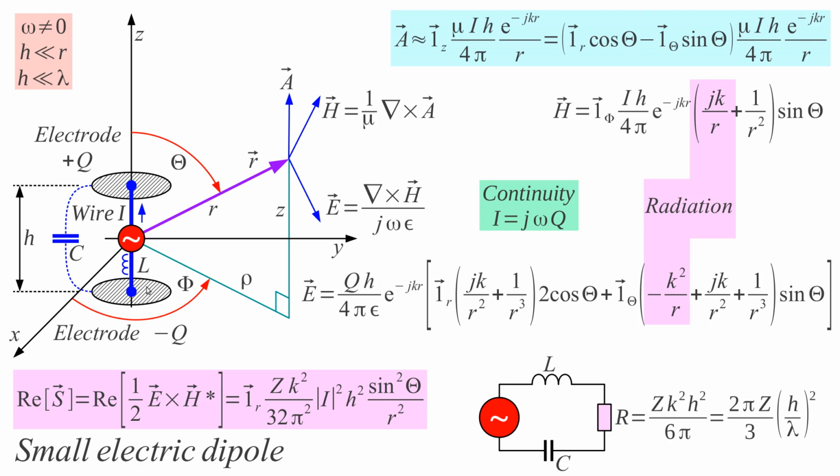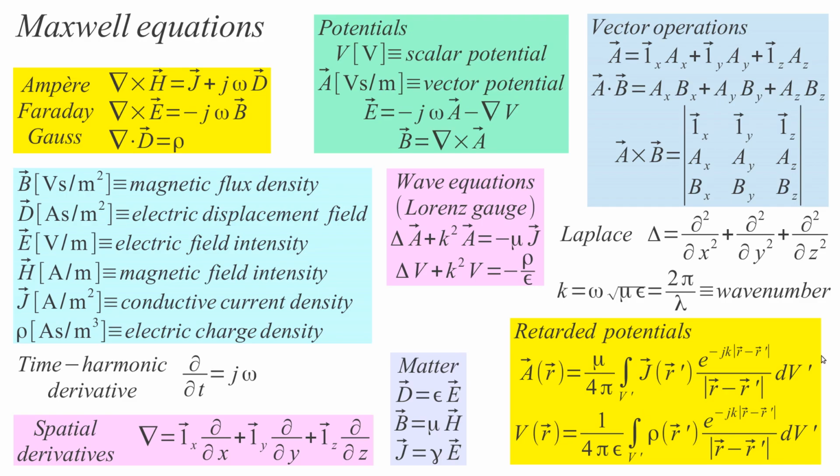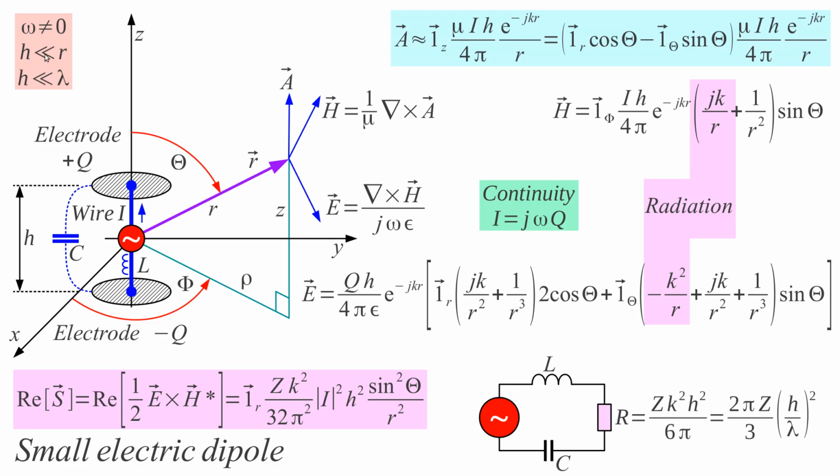People simply went to very long wavelengths because the electrical spark was a much more efficient generator for longer wavelengths than for shorter wavelengths. They were much more efficient at lower frequencies. This was the reason why. But all these antennas are inefficient, so a segment of wire that is short compared to the wavelength is inefficient. But we can calculate it because in this case this formula turns out very simple. There is no integral here. We don't calculate the whole integral. There is simply multiplication under these conditions.